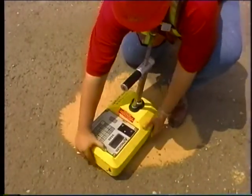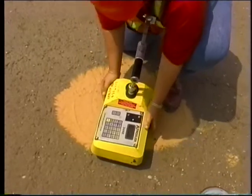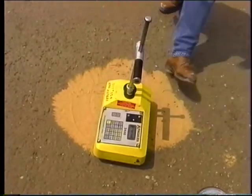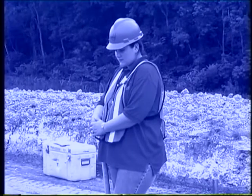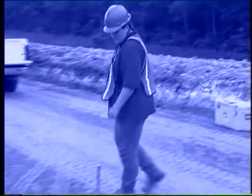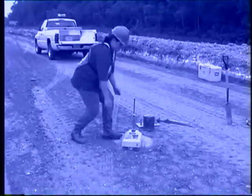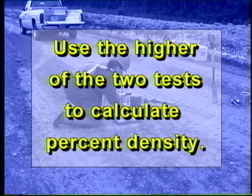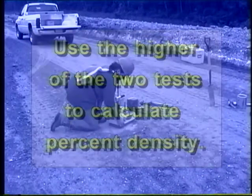If the dry density of any test is more than 48 kilograms per cubic meter, or 3 pounds per cubic feet below the highest dry density of the 3 tests, reseat the nuclear device in the same orientation as the original test and rerun the test to verify the results. Use the higher of the 2 test results, original and retest, to calculate percent density.